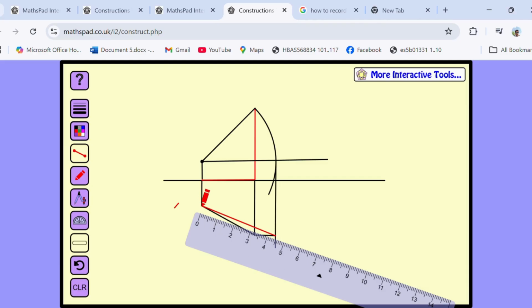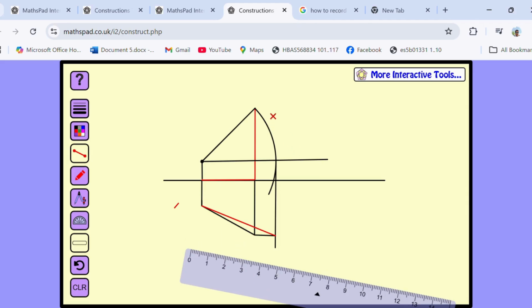And the angle made by this true length with this horizontal axis, with this reference line, is theta v. And similarly, you can rotate this line and you will get theta as well. So now I'm going to repeat the same procedure, but this time I will start from AB, not from A prime B prime. So we'll repeat the same thing, and whatever true length you get, that length is similar to this length, and whatever angle this line makes with horizontal axis will be your theta h.